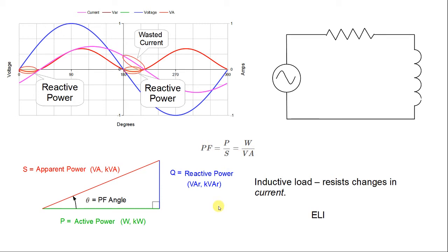So let's just take this circuit as an example here, and let's say that my power is 8 watts. My active power is going to be everything that is above the x-axis here, and I'm saying that is 8 watts. My volt amperes, my apparent power, is this whole graph here.